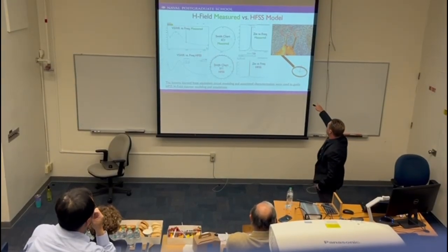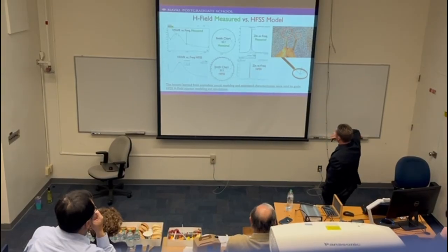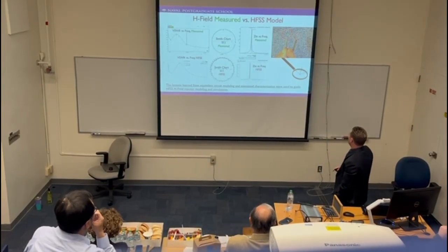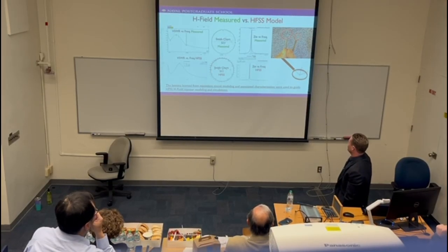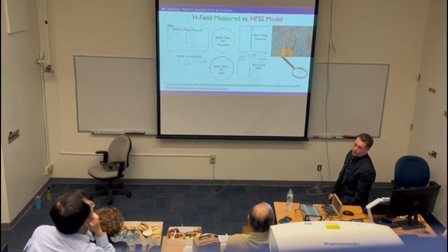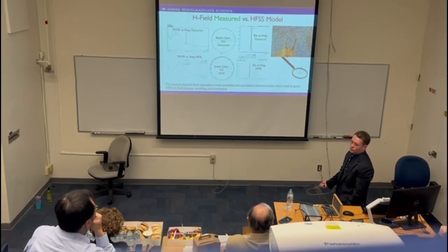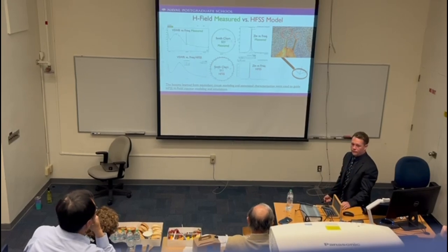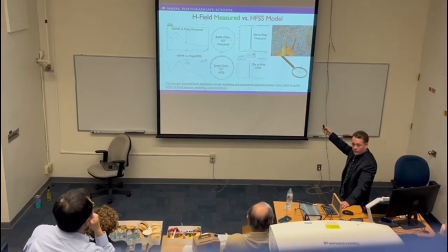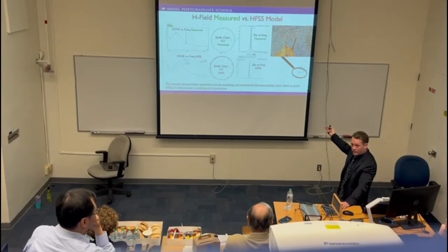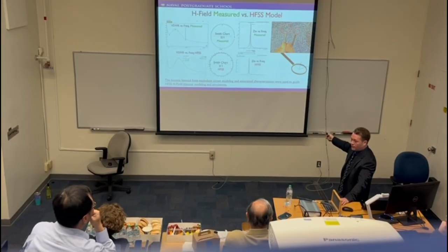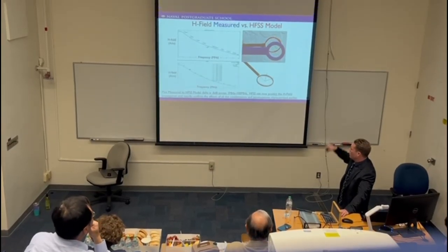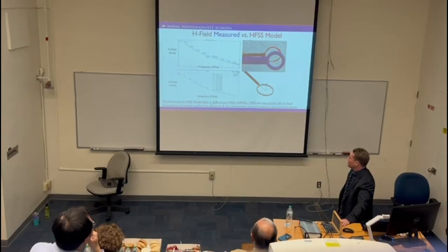You can see here on the bottom, this is my HFSS 3-turn coil. That's like 33 millimeter diameter. I got my 11 millimeter and my 20.5 millimeter up on the top there. Again, unshielded, and I can also do the shielding as well in HFSS. And it's really cool. It shows essentially that same cut down of the E field, drastic cut down of the E field. I just put in the parameters that it is copper, for instance. I put in the basic permeability of standard copper, and it cuts down as expected. And here's the overlap of measured versus H field.